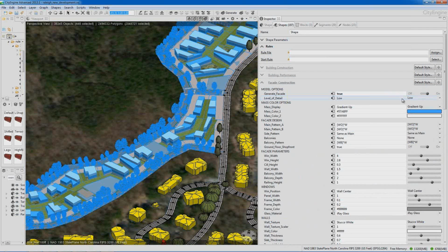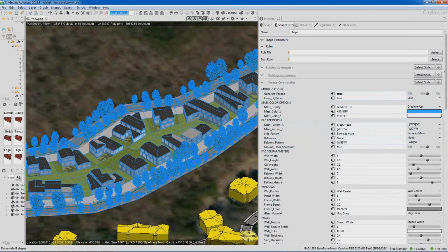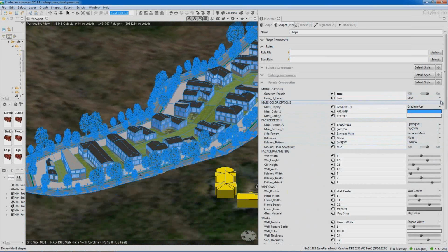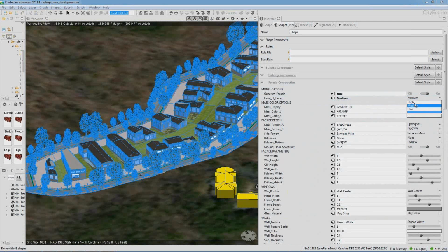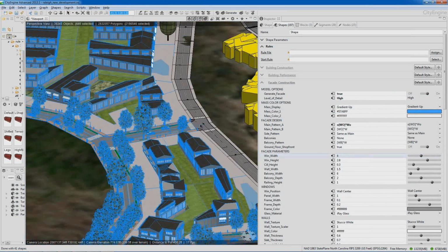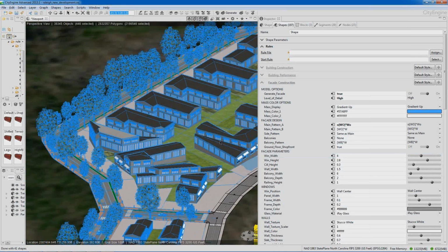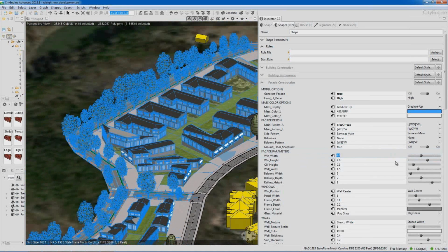So under the facade construction, let's just turn on the facades, and you can quickly visualize how those buildings would look. And that's going to add more metrics because there's more geometries being created on the buildings, which give us further reporting for window area or wall area, surface area, floor area ratios that are more accurate, number of windows, number of anything on the building could be reported. And that's the value of procedural modeling. Any element that you model with a rule can be reported on and has intelligence.